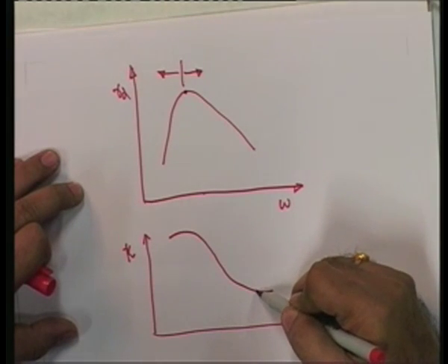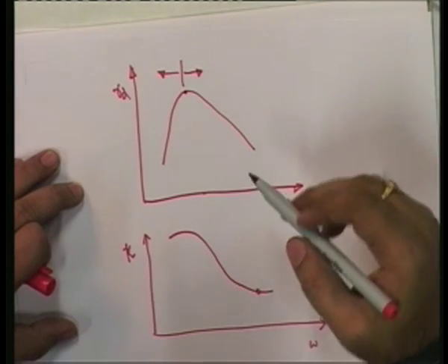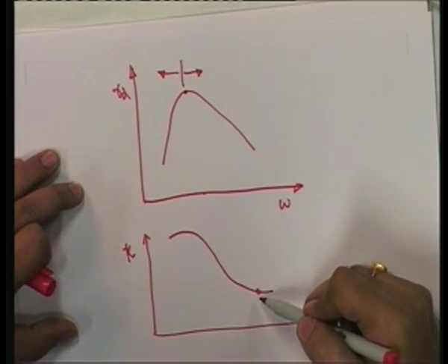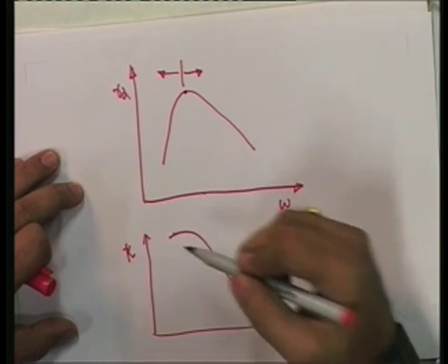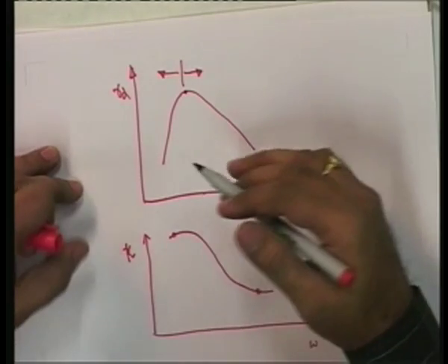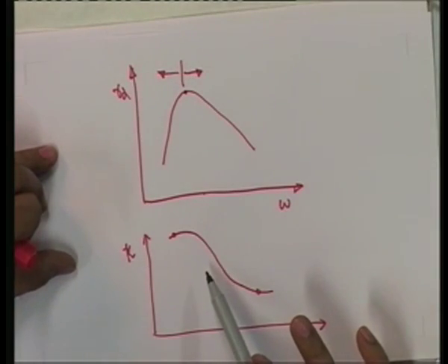So, on the wetter side of the optimum the coefficient of permeability will be less, on the dry side of optimum the coefficient of permeability will be high. So, that reason is attributed to the type of the soil structure which is prevailing at that particular moist compacted state or in its natural state.